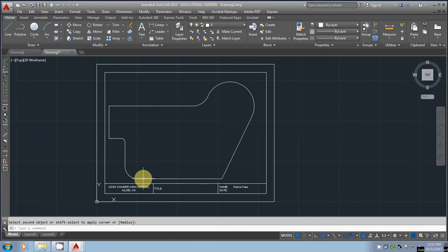The next step that I want to do is offset all of this to create an area where fluid or air could pass through if this was a gasket used in a small engine. To do that, I could offset each one of these pieces, then trim, but to make this go a little faster, we're going to turn this into a polyline so it's all one piece of line geometry. To do that, I'm going to come up here to modify, choose the drop down. I'm going to say edit the polyline.